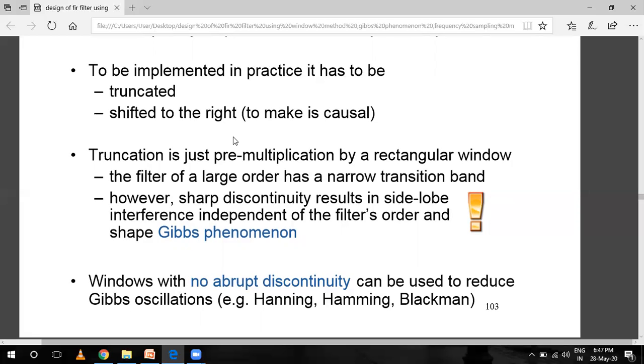And if the signal has no frequency content that is truncated, the Gibbs phenomenon does not occur. For example, applying a low pass filter to a single frequency sine wave creates no ringing effect.